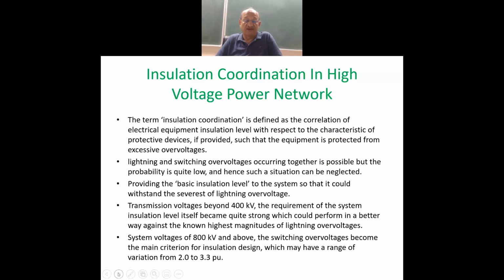Lightning and switching overvoltages occurring together is possible, but the probability is very low. So they are not considered for the situation when lightning and switching may take place together. There may always be some time gap for these two types of overvoltages taking place in the network.